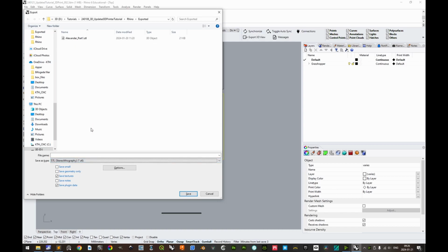Exporting to this file format will create an automatically meshed version of your model and will include only the actual vertex positions for each meshed triangle for each object, and will exclude any UV data, vertex color data, material data, and any other data which would be irrelevant for 3D printing.